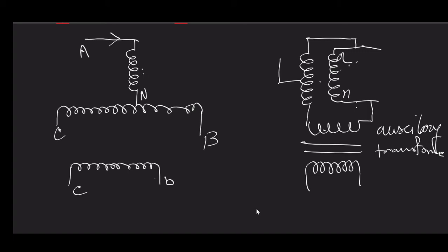But the problem is that if you do not connect a load with this, and rather connect the same amount of resistance across this and this, you are going to create an unbalanced situation. A heavy current will flow through A and also B, C, the phasors will not remain balanced, and you cannot go for a per phase circuit.